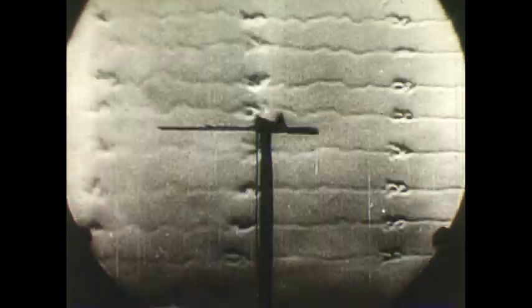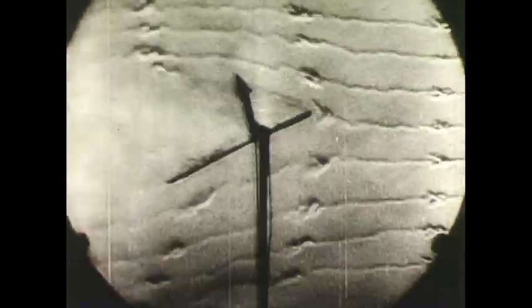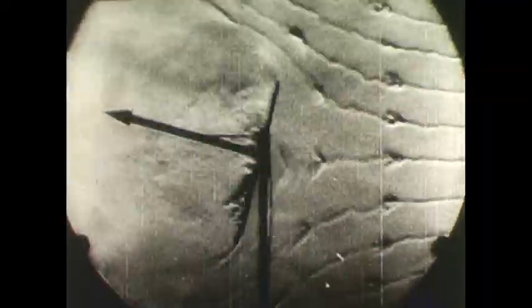The plate is deflecting the air downwards and retarding its forward flow slightly. In doing so, it gets an exactly equal and opposite reaction from the air, represented by the arrow acting upwards and backwards. It is obvious that if this plate were left loose, it would be blown upwards and backwards before it dropped. The resultant air force increases as the angle of attack is increased. It reaches a maximum when the plane of the plate is perpendicular to the direction of airflow.